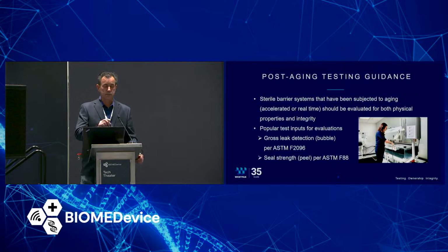So the package is referred to as the sterile barrier system, and subjecting it to accelerated or real-time aging, regardless of those two, it still needs to have physical testing to be evaluated at the end of the time period. So at the end of whatever activity you're doing, you need to show that the integrity has been maintained. And that can be through gross leak detection. That's a common test. There's also dye penetration. And then there's seal strength testing. That's a strength test. Or burst testing.